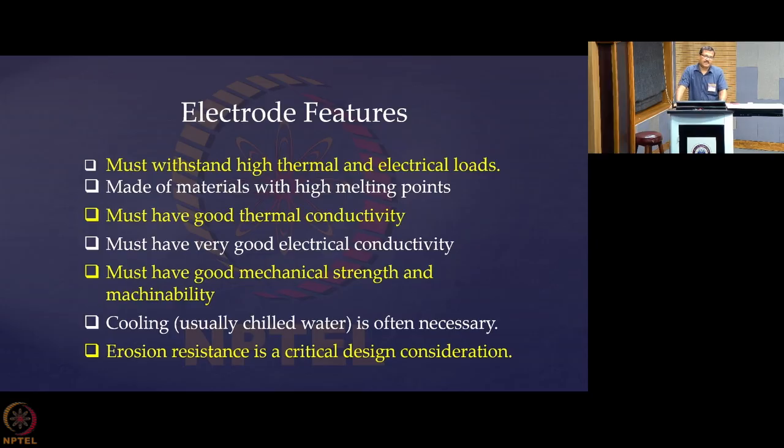And there is another thing, that arc constriction occurs over the cathode as well as the anode surfaces, and when such constriction occurs, huge current density occurs because of the very tiny cross section of the joining point. So, through a very small area of cross section, huge current passes through, and that generates a large amount of heat over a very small zone and makes the material melt.